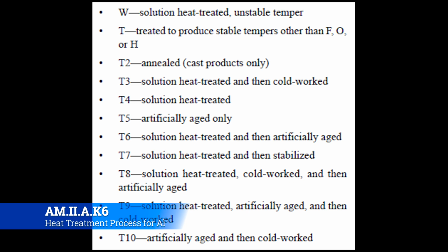Where you're going to see this most prominently is in the structural repair manual. Whenever you say, hey, look, there's a hole in this airplane, so we're going to cut the hole out and put a patch on there, what metal do we need to order to get this repair going? Then you'll get in the structural repair manual. It'll say it's 2024 T4 or whatever, and that's where you're really going to want to pay attention. But just so you can be a competent mechanic, you can know a little bit about that aluminum by simply taking those T numbers and breaking them down.